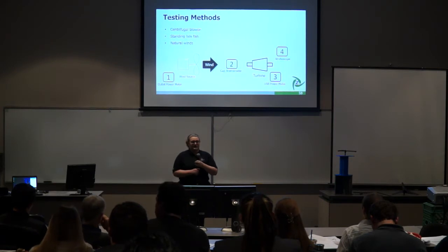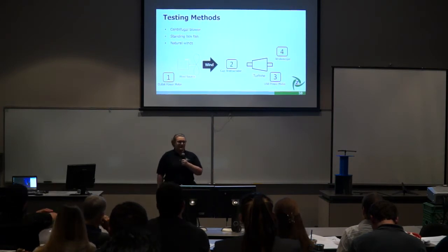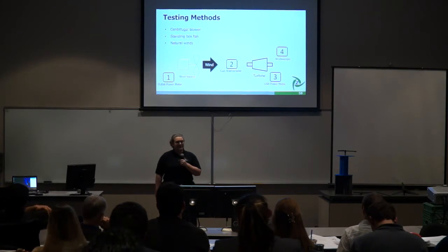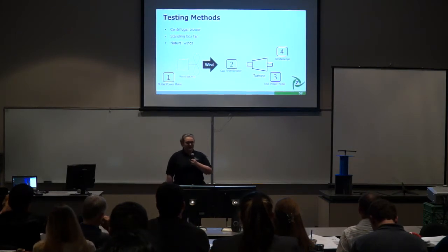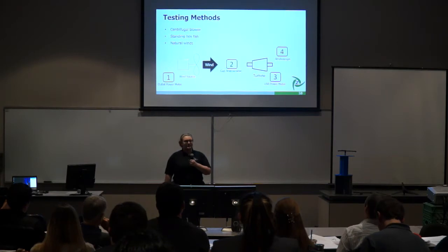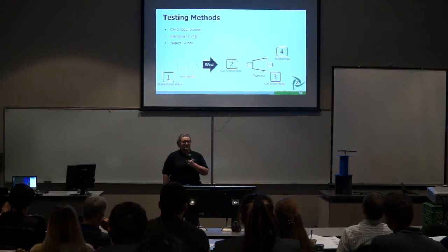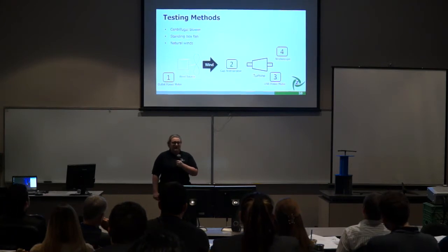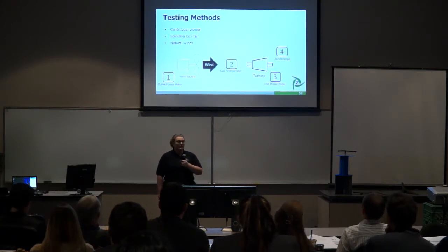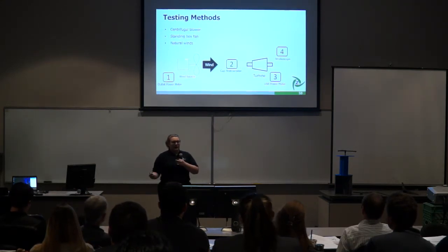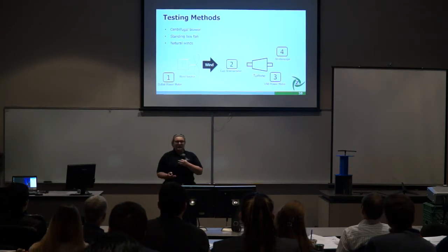On the screen is the testing method for Project Zephyr. We have the opportunity to use 3 different wind inputs: a centrifugal blower, a standing box fan, and natural winds. At location 1 is the outlet power meter. When using the centrifugal blower or standing box fan, this will be plugged into the wall outlet and the wind device will be plugged into that. Then we have our wind source and our wind moving towards the cup anemometer at location 2. This is placed between the wind source and the wind turbine so that we can gauge an accurate wind speed going into the wind turbine.